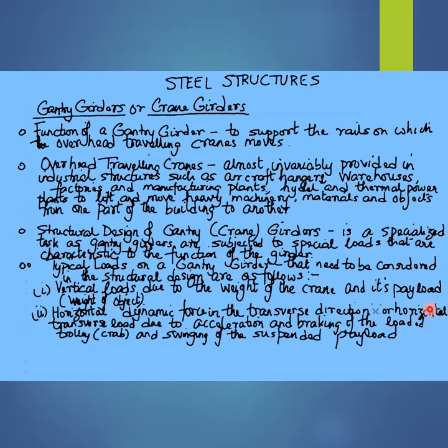The horizontal dynamic force in the transverse or the horizontal x direction, termed as the horizontal transverse dynamic load due to the acceleration on braking of the loaded trolley, known in common jargon as the crab of the crane, as well as the swinging of the suspended load in the horizontal transverse direction.